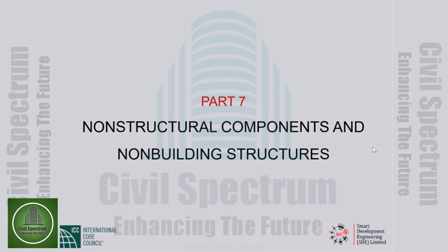So it is the deflections under the strength level seismic forces that are important. I would say keep the gravity in place. Dead plus live would be fine. Dead plus a little bit less than the full live load would be fine. But to look into load combinations is not something that is called for.